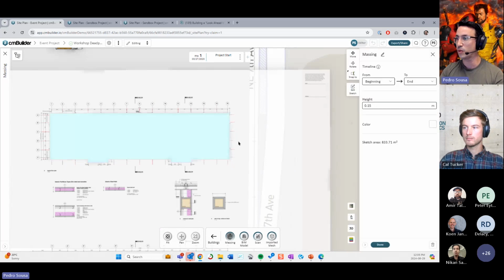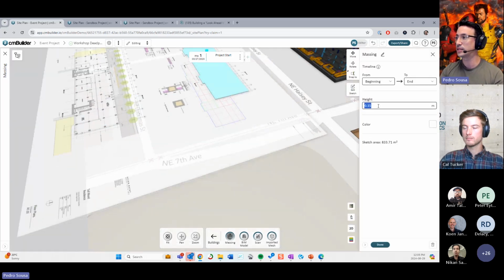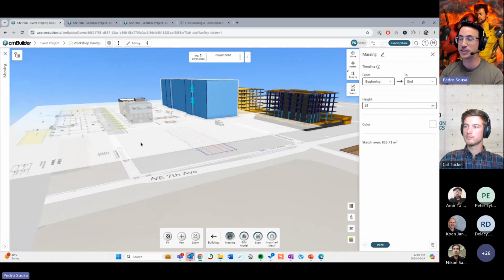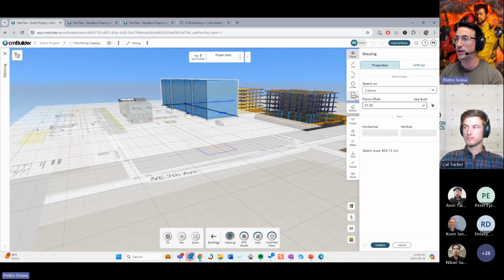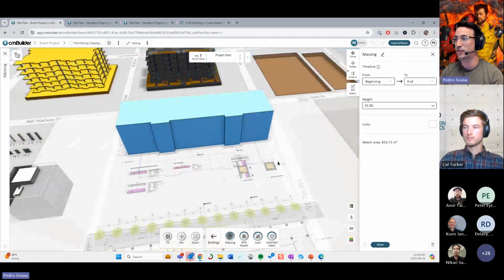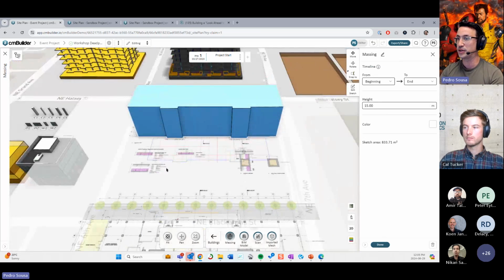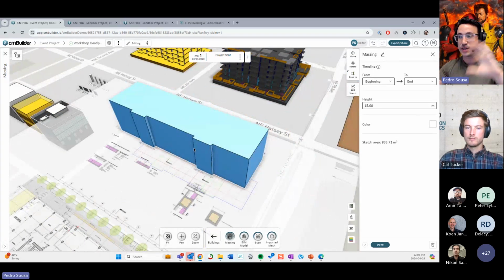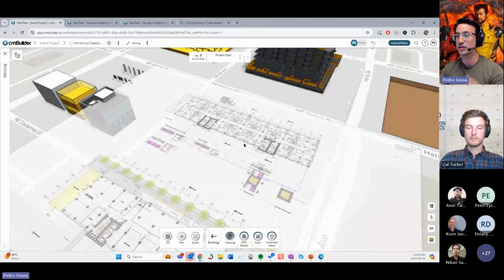So when I create a simple massing, you're gonna see that the massing itself is just one simple extrusion from that shape, right? The massing showed up over here on top of the drawing because when I created my sketch, I selected the drawing as a reference, so it's bringing the massing from the top of the drawing, right? So this is one situation where we create something like this. When are you using this? Whenever you want to work very fast, and you just want to create shapes that you can plan around, right? So if this is the case, you can use the simple massing.